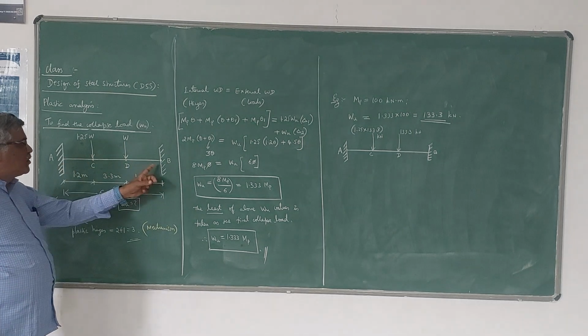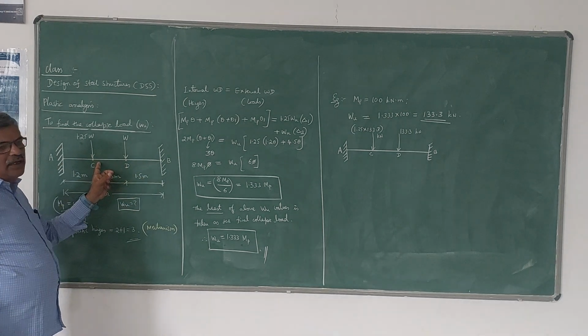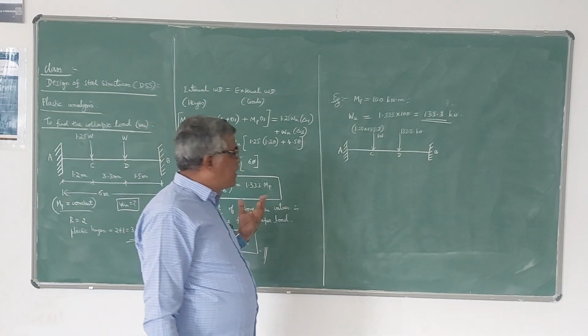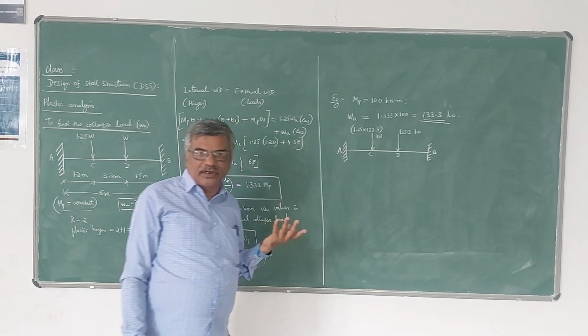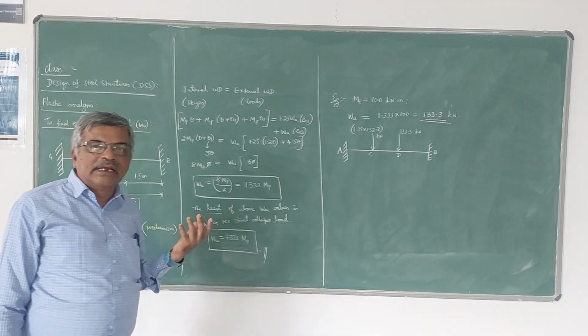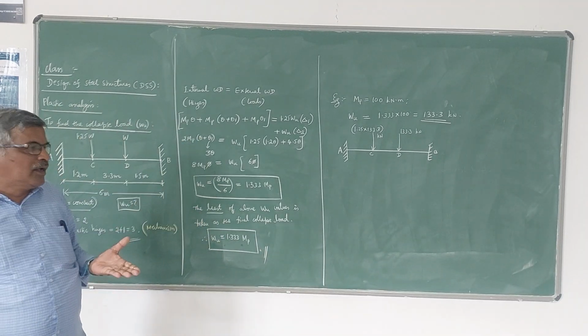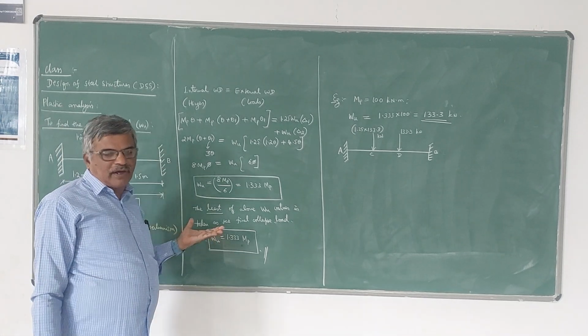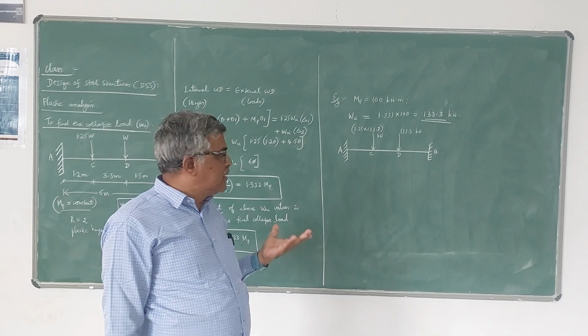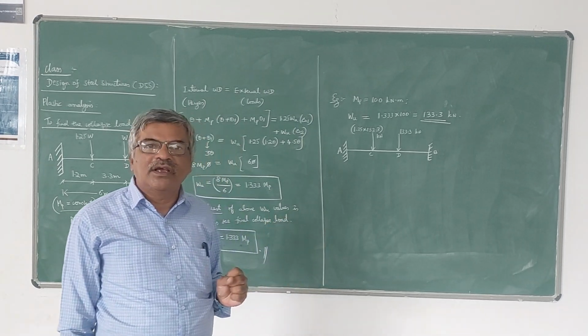One at these 2 supports and the other one under the load. So calculate WU using the kinematic method, internal work done equal to external work done. Then get the value of WU in both the cases. Take the least value as the final collapse load value. Suppose if you get equal values in both the cases, then you take that value itself as the collapse load.